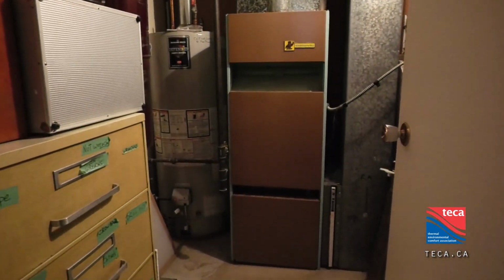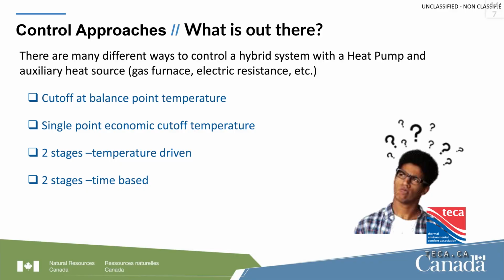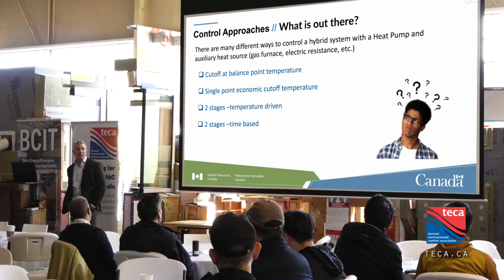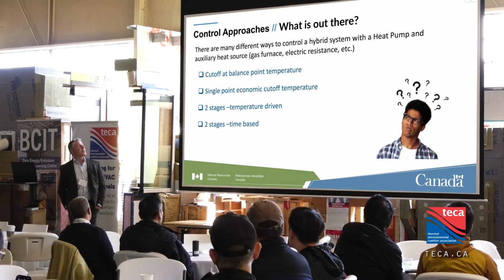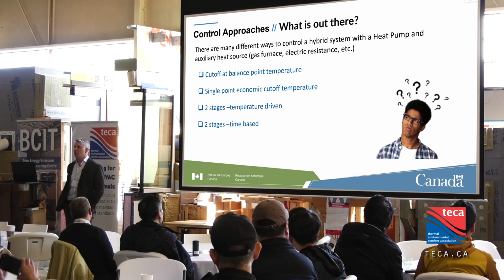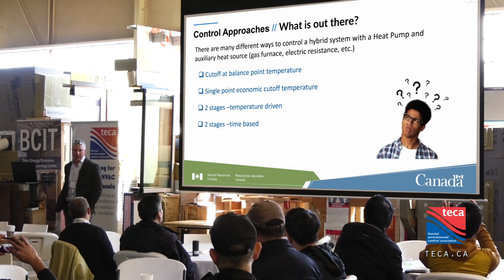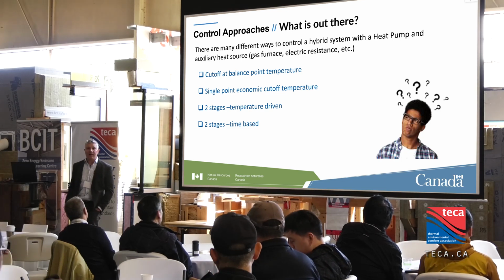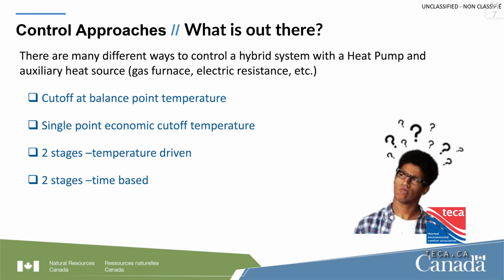So we're going to talk mostly about 3 different approaches, but there are 4 listed over here. The one we've already been talking about is the balance point, in regards to temperature dependence. At some point, we'll switch over to our supplementary or auxiliary heat at a certain temperature, where the heat pump itself is having trouble keeping up fully, or 100%.